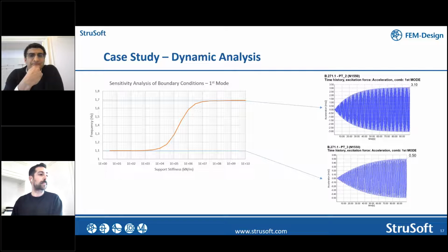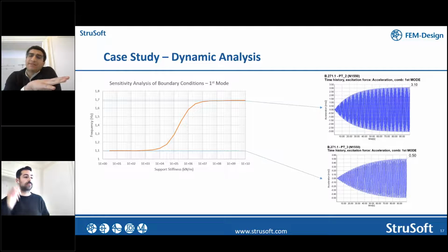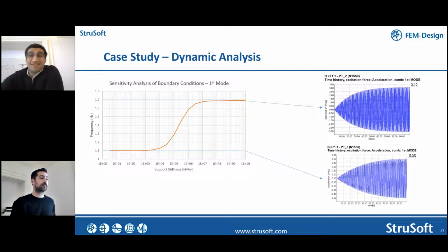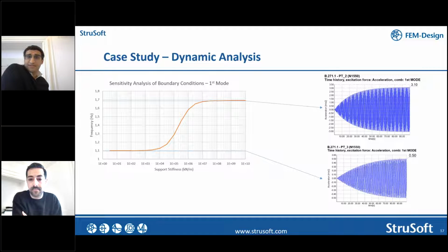Yes. So the thing is that, again, going back to the parametric analysis, this is where the code allows you, from a stiffness strategy perspective, just going back to what we have already discussed, to actually reduce the applied load. That factor is related to whether your pedestrians, your crowd, are going to be synchronized or not.